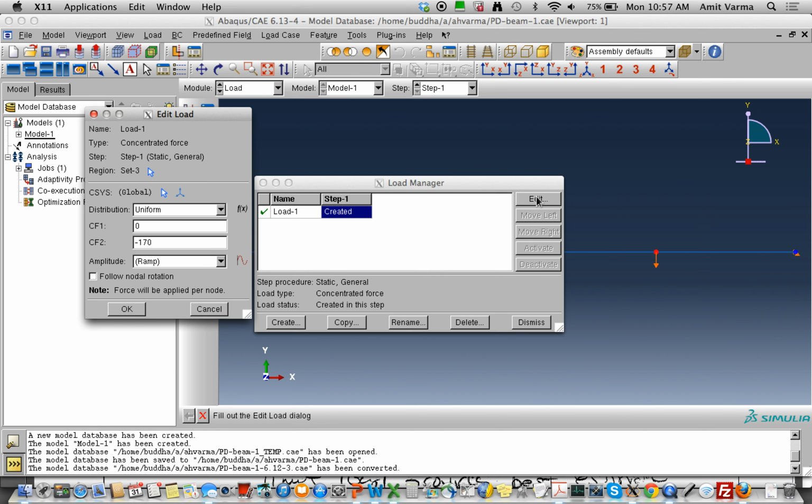Displacement control may or may not be able to find the solution, but the Riks method will always be able to find it because it will be using an arc increment. It's always using a positive increment on the load displacement to find the next state of equilibrium. So from the current state of equilibrium, it throws out a little arc to find out where equilibrium is possible. And if it can find equilibrium anywhere around that circle, it finds that point and proceeds further. There's a whole nonlinear formulation that Riks developed and been implemented as the modified Riks method, but that's not something that we're going to talk about.